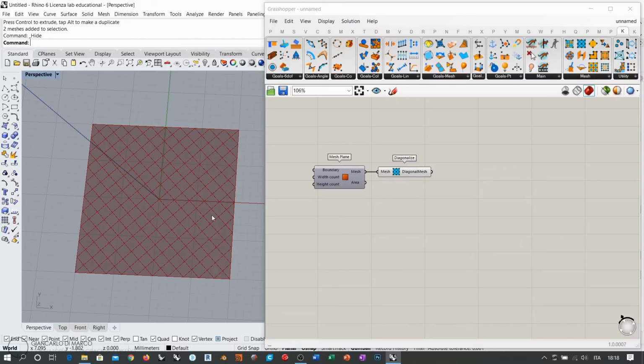We can differentiate the pressure. So I want a pressure with a value of X acting on this area, and I want a pressure with a value of Y acting on the other area. But if you want to do this, you need to separate the mesh into two separate sets of polygons, and then you must apply different pressures to the different areas. So you must basically work by separating both the geometric system, like the mesh, and the pressure values.